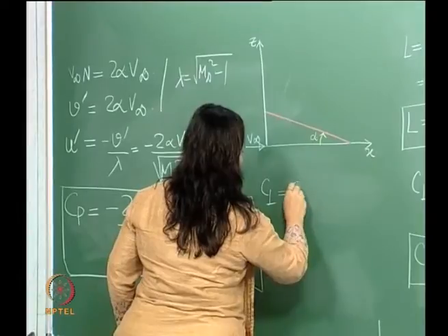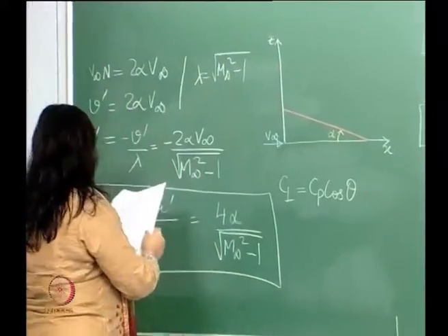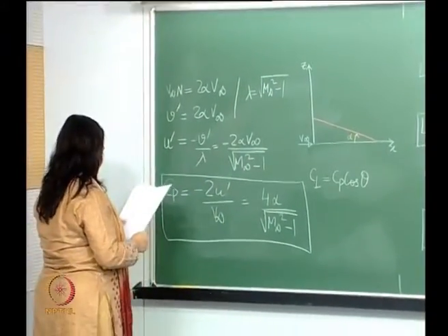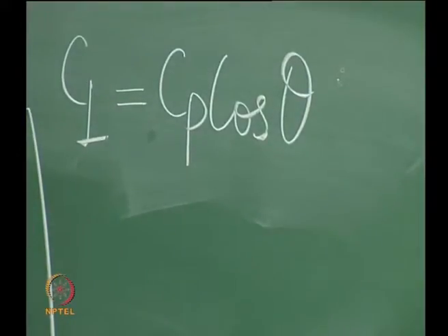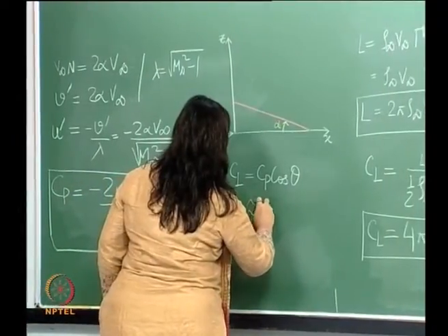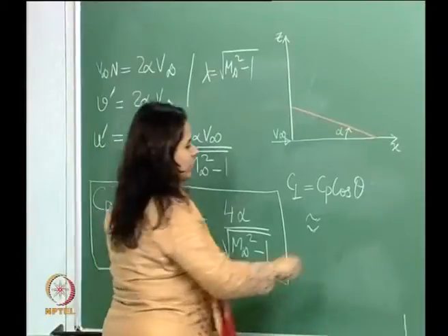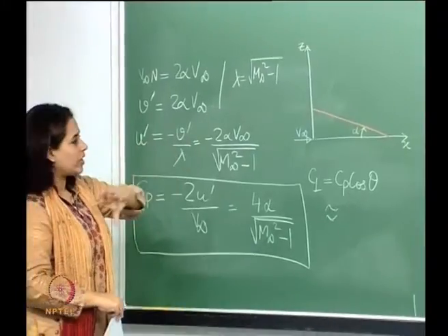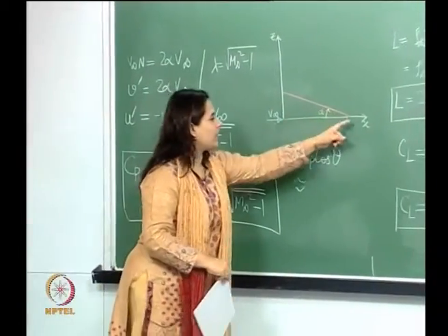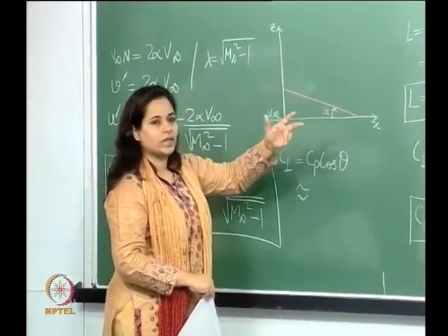Okay. So, now CL is the lift, which is Cp cos theta. Okay. So, if you look at this particular case over here, this becomes, as theta tends to pi, we go over. So, basically what we are doing here is we integrate this over the entire length of the airfoil, going from 0 to pi.